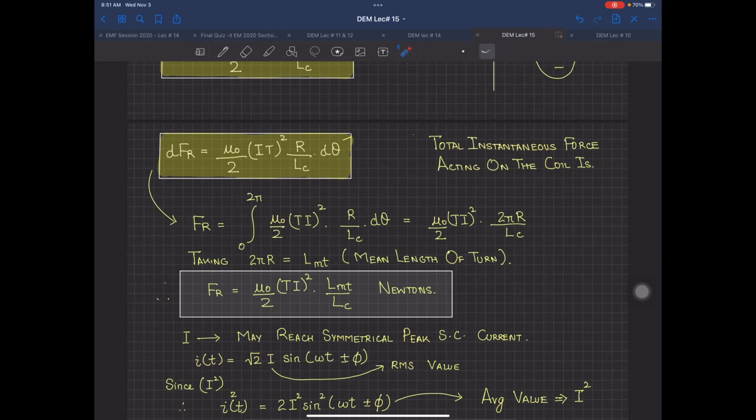That's why, I don't know whether you have reached up to that point or not, but whenever you are designing a 3-level protection, step protection, have you read it yet? 3-step protection. I guess after mid it will be coming. Whenever you have that 3-step protection for a generator or a transformer with a generator, you always keep the first relay that has to trip in half of the cycle, which means within 10 to 15 milliseconds you have to